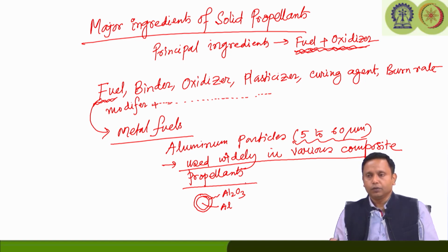Okay. Now, the choice of the metal particles is coming from their high energy density compared to the normal hydrocarbon fuels, even polymeric fuels, considering their heating values. Generally the metal fuel heating values are higher than the hydrocarbon fuels, but not always. For certain metallic fuels the heating values are higher, particularly the volumetric heating values.